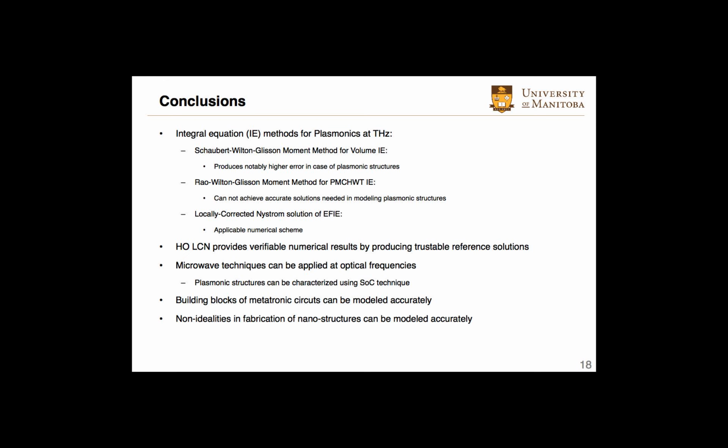Integral equation method for plasmonics at terahertz frequencies. We studied the volume integral equation and the surface integral equations using low order methods. They are not efficient because for the volume integral equation they produce notably higher error. The PMCHWT, which is the surface integral equation, cannot achieve accurate solutions in modeling plasmonic structures because it has high attenuation, but the high order locally corrected Nystrom method can accurately model the plasmonic nanostructures.